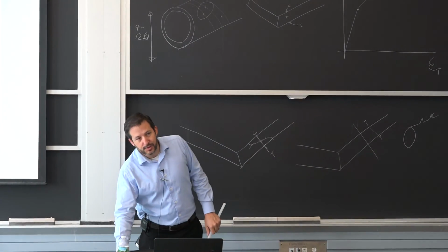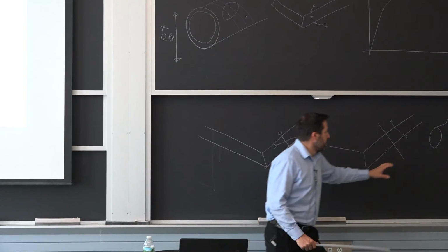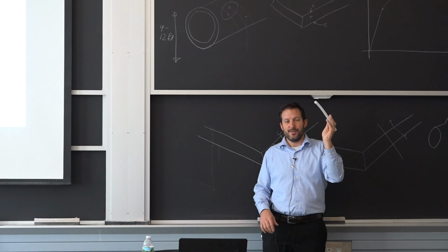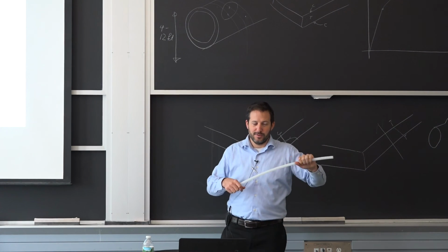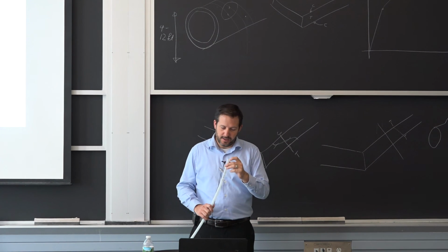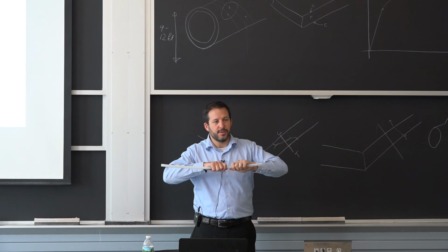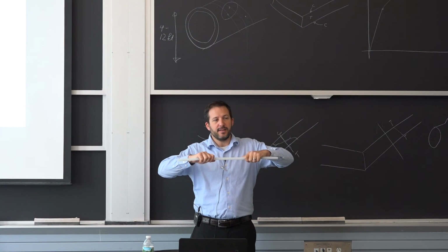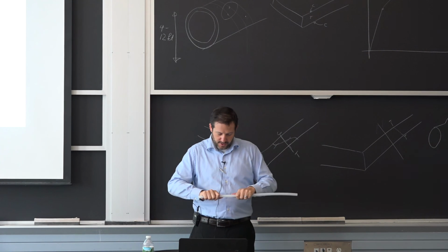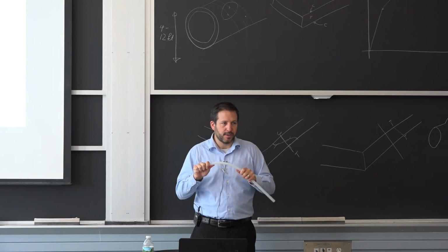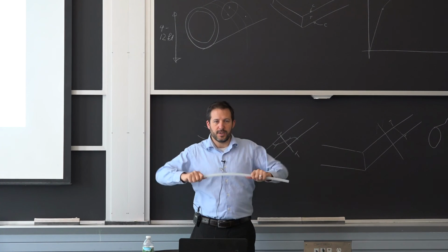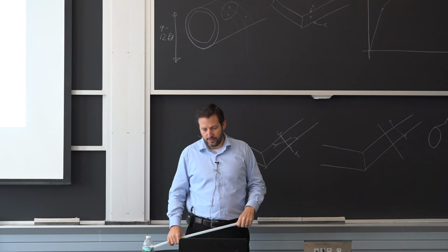And when I talk about service, the biggest load that would get this grabbing to pull out is not the pressure. I mean, this is a small diameter pipe, so the tension, let's say it's 100 psi, you've got only 1/8 of an inch, so we're talking about 20 pounds of tension. But when I start bending it like this, let's say it's going through some thermal cycles in the building, or there's something going on, these are the highest stressors. So if it was going to try to move and leak, it would be during movement like this, as opposed to just the tension from the pressure.